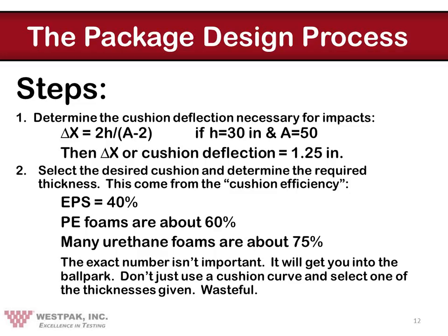Various types of cushion systems have different dynamic responses. They respond differently. So some deflect a lot before they bottom out, some not very much at all, and most of them are in between. Even if we are using cushion systems other than polymeric foams, the same deflection calculations are required. Remember, the product really doesn't know or care what kind of cushion surrounds it. It only knows how much shock is transmitted to it.